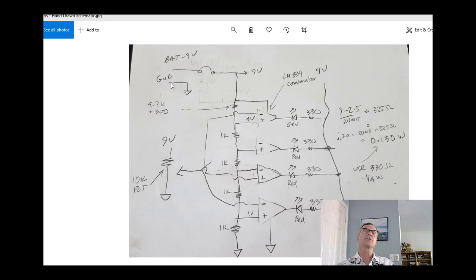And on our printed circuit board, we're going to put what's called a wire pad here and a wire pad here, and we'll maybe even mark them battery and ground on the printed circuit board so we can see what goes there. Those will have red and black wires that will probably attach to them, and then they'll go over to our 9-volt battery.